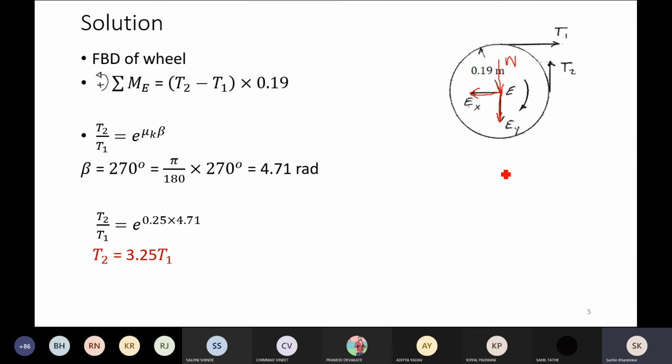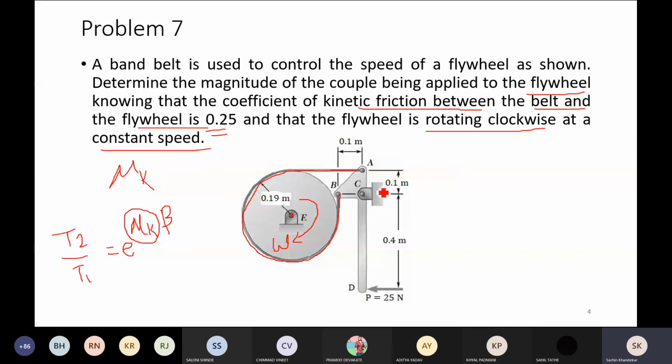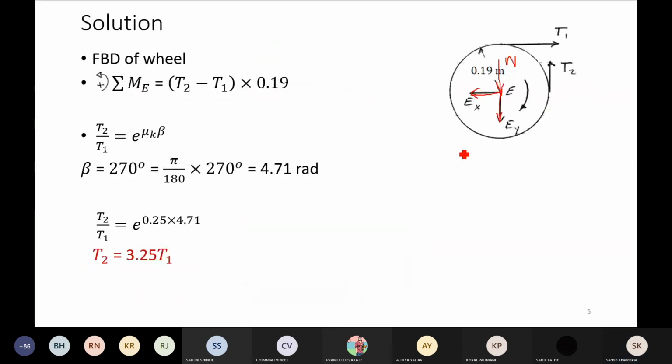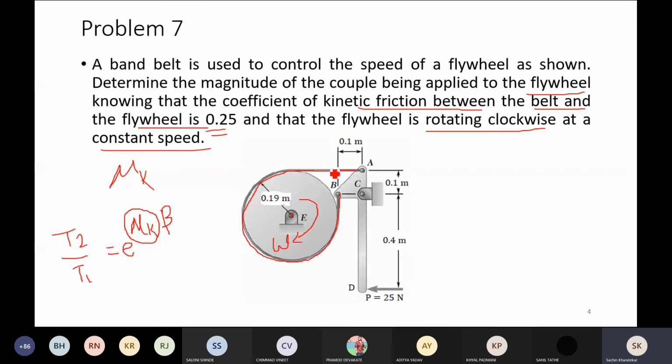Okay, fine. What is the next force now? Now we are drawing only the FBD of this particular flywheel. We have to detach. We have already detached this pin support by its reaction, and hence we have shown here the two reactions. We have replaced the hinge support by the two reactions. Similarly, we are going to detach this flywheel from this flat belt also.